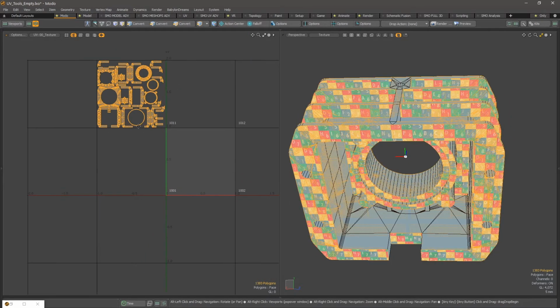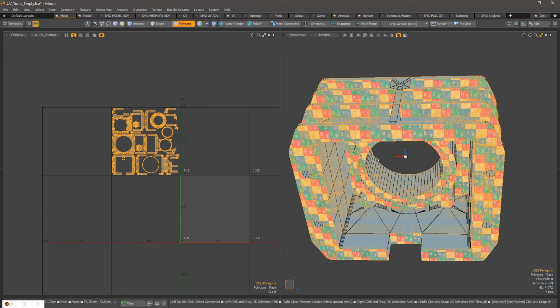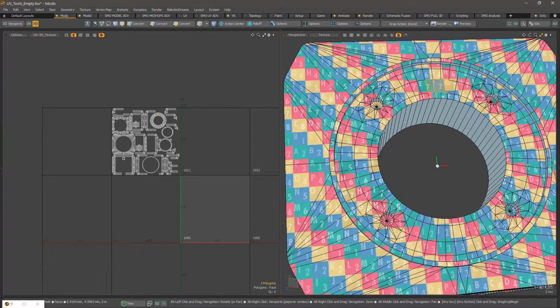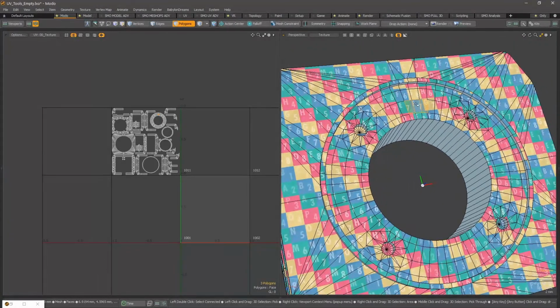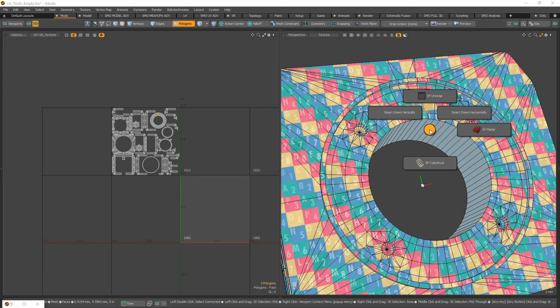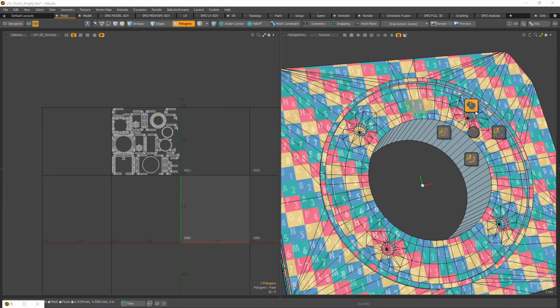So this is for the planar projection. You can do this also with some selection over here. I will just do this on similar touching, just to show you. So I press the Q key, I go to the planar projection, I will do the selection similar touching, and I will do this on the free mode.